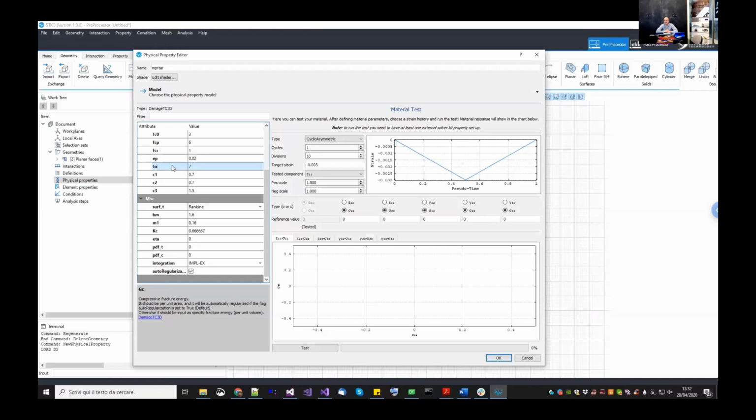Depending on which papers you have read, someone takes the diagonal of the element, someone takes the square root of the area, if an element is kind of regular. In OpenSees, they do something different. They take the minimum distance between the different nodes.